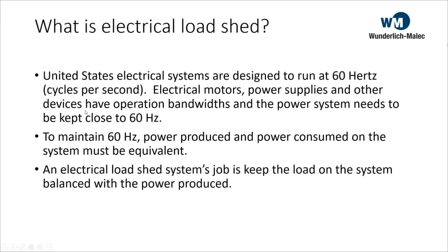There we go. So what is electrical load shed? I think everybody probably knows that here in the US, we run a 60 hertz AC system. And so electrical motors and other loads have got to stay close to that 60 hertz to operate effectively. So an electrical load shed system's job is to keep the load on the system balanced with what the power production that's available in that system. Let's move to the next slide.